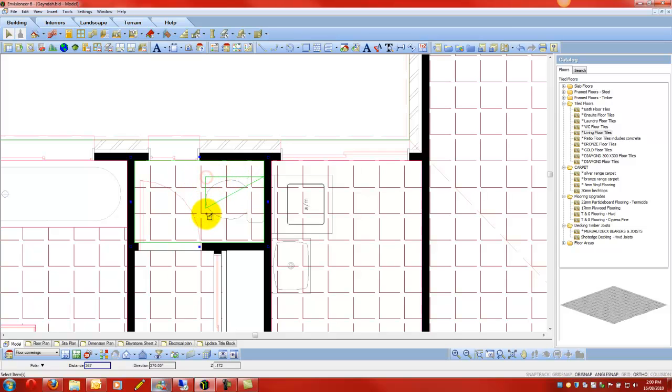and until it hovers. Here we go around the toilet, because the toilet has an area around it which is in a square grid, so if you just keep going past in a straight line on ortho, all of a sudden it'll go around in a circle, you know that's the point to click to, and that'll line up with the outside edge of the toilet, and just go to the wall, click, right click, finish.